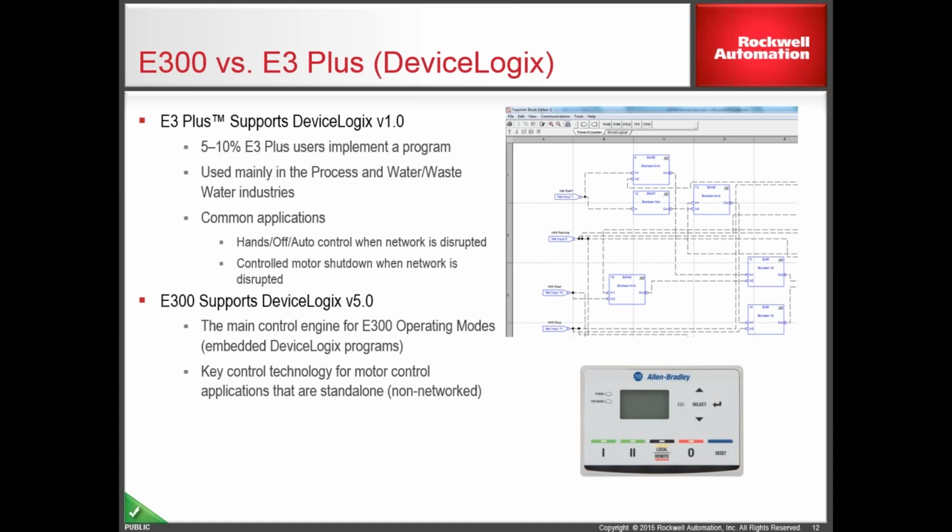In version 6 of the E300, we've allowed you to go in and actually customize your DeviceLogix programs. So if you've got some type of special configuration that you want to use, you can easily go in and edit the DeviceLogix. And if you look at the picture here, it looks really similar to a Studio 5000 application. So you can use ladder logic, or you can also use function block diagram programming for that.